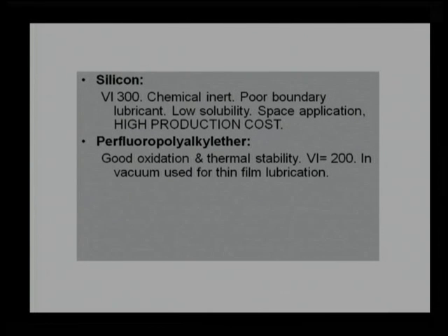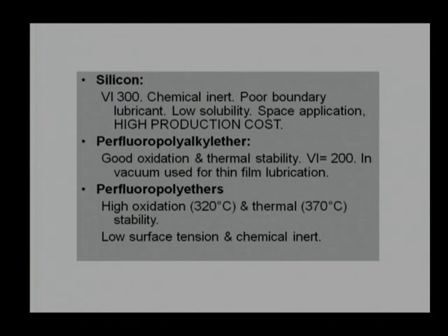There is a similar kind, the perfluoropolyalkyl ethers, perfluoropolyethers. Their VIs are high, they have very good thermal and oxidational stabilities, and they can even be used in vacuum applications. You can see for perfluoropolyethers, the temperature limit is 320 degrees centigrade, same as silicon oil. They are also chemically inert.